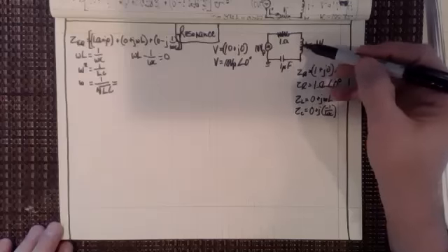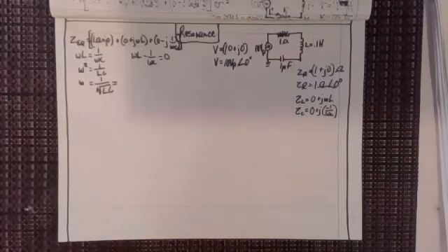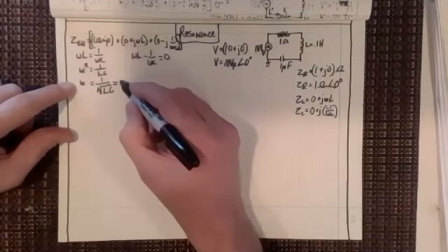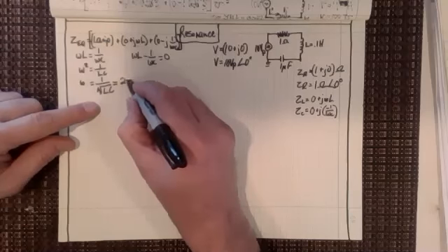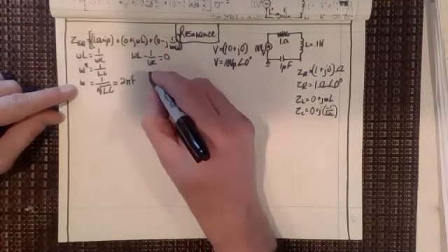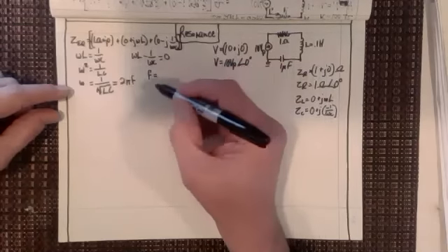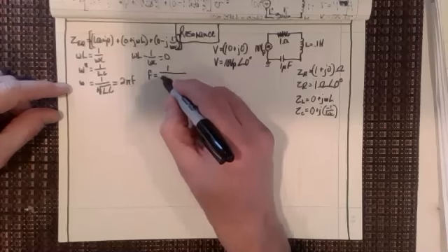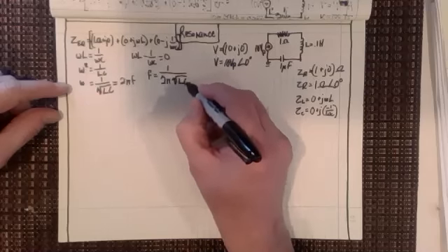And in fact, because they have 0 for resistance, both of their impedances are going to cancel each other out. Does everyone see how that works? And it's at a magic frequency, isn't it? Now we know that omega is going to equal 2 pi f, right? Because I say omega, you say 2 pi f. So if we wanted to find out what that magic frequency was, we would just have that frequency is 1 over 2 pi times the square root of LC.